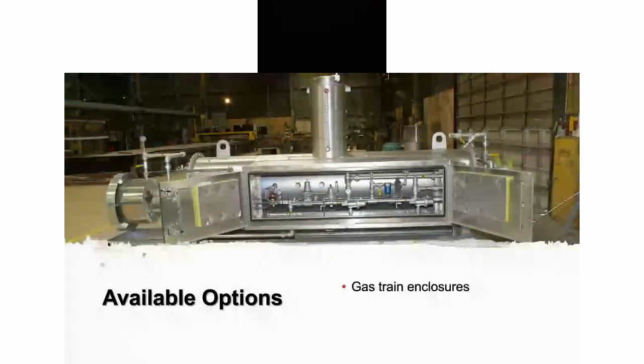Next option is an enclosed gas train. As you can see, there's a cabinet with insulation, and this was designed for certain customers in very cold climates, and maybe a situation where they want to keep the gas train outside of the elements, kind of keep it protected. For this cabinet, we cut away the insulation to be able to use that radiant heat from the shell and keep that area warm, and it kind of closes in with insulation, keeps it nice and warm.